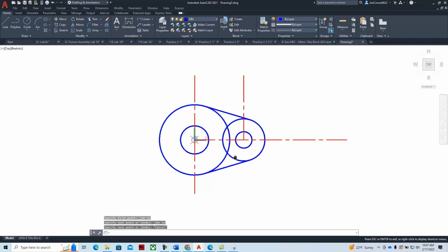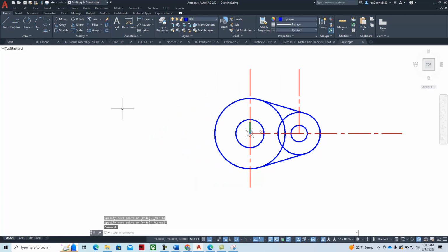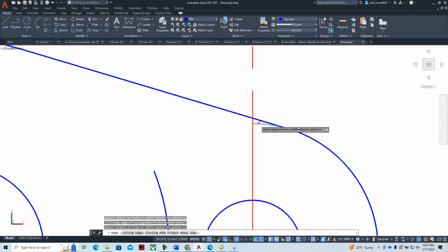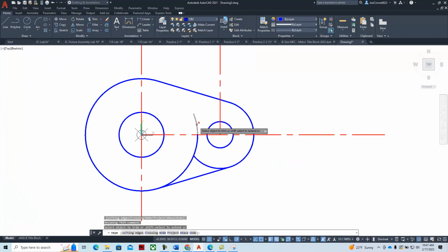And then we'll clean this up, and then we'll mirror it to the other side using the trim command. You want closed boundary shapes, meaning endpoint to endpoint, and you want to avoid anything that would be like this. You want nice, clean, smooth transitions for your boundaries.